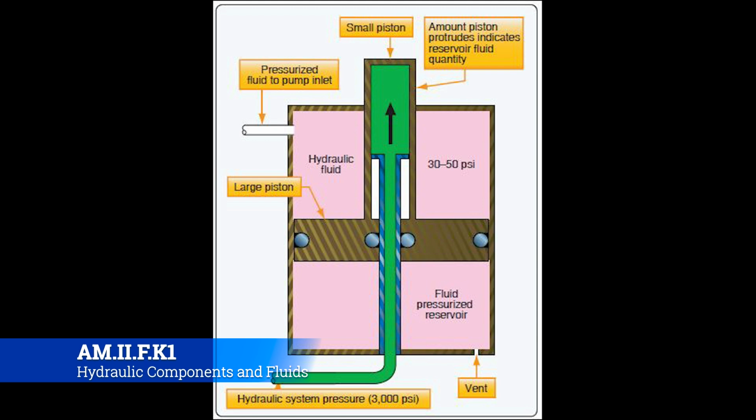This graphic illustrates the concept behind the fluid pressurized hydraulic reservoir. There are five parts: the pump suction port, the return port, the pressurizing port, the overboard drain, and the bleed port. Fluid is supplied by a pump through the pump suction port, and fluid returns to the reservoir from the system through the return port. Pressure from the pump enters the pressurizing cylinder at the top of the reservoir through the pressurizing port. The overboard drain drains the reservoir when necessary while performing maintenance. The bleed port is used as an aid to servicing the reservoir.